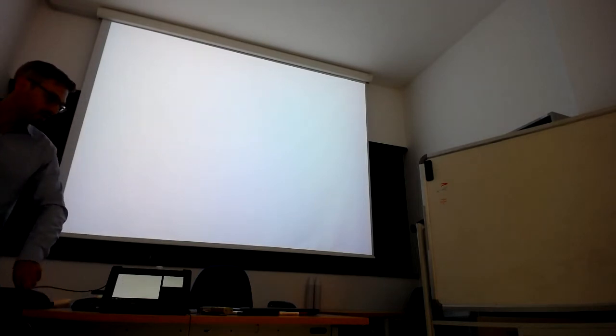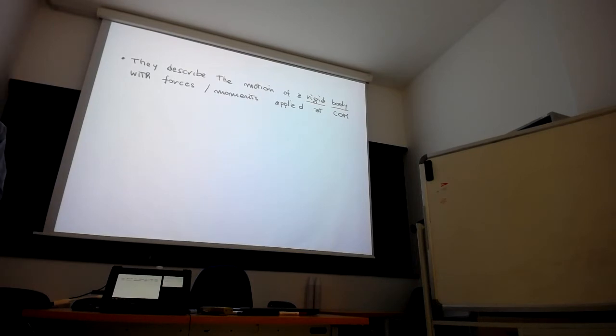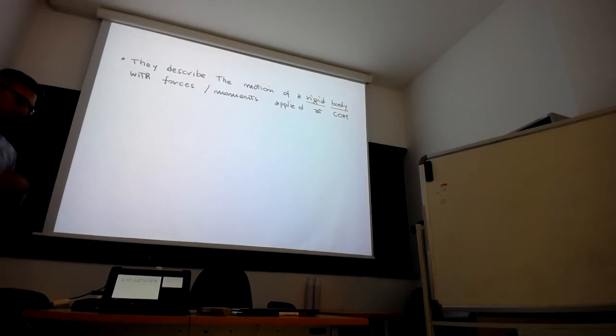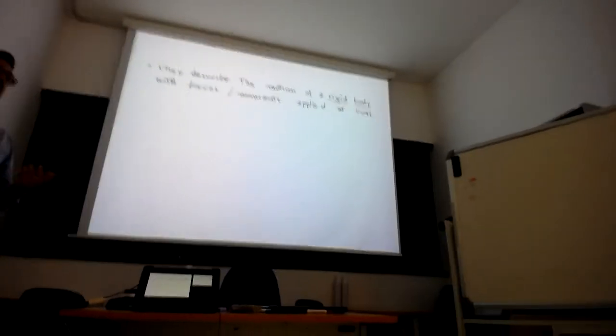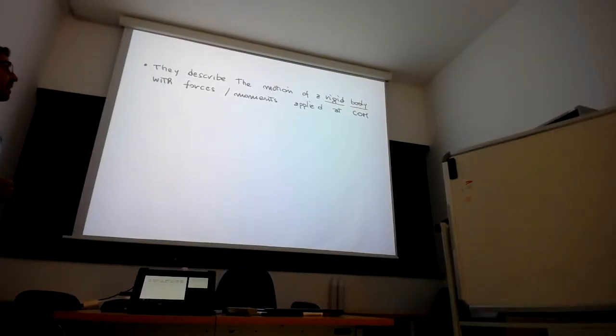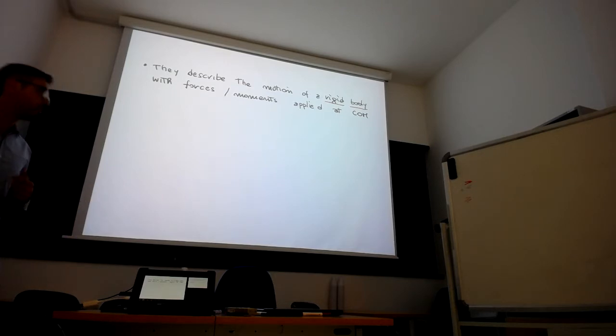Newton-Euler Equation, actually. So we arrived to define the floating-base dynamics, the dynamics for a floating-base robot, seeing that a different parameterization of the generalized velocity using the velocity of the central mass was leading to a decoupled equation, one underactuated and one actuated. And the underactuated one was corresponding to the Newton-Euler equations. So in particular, now we can detail the Newton-Euler equation and see how they are written and how there are smarter ways to write them in order to speed up, for example, optimizations.